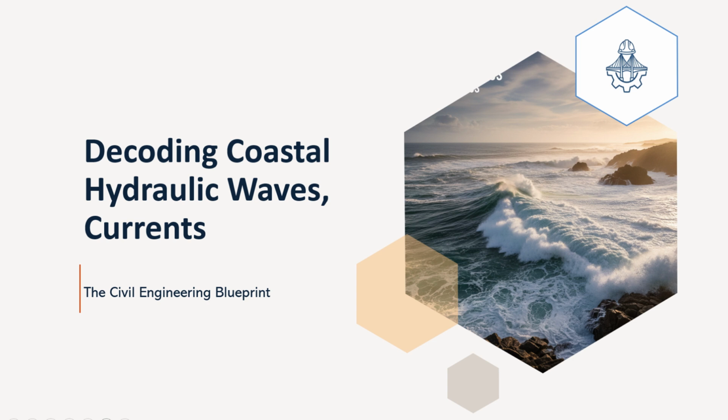Moving beyond reflection, let's consider 4, wave diffraction, the fascinating way waves can sort of bend around obstacles. This happens when waves bend and spread out as they pass an obstacle or an opening, like a breakwater tip or a gap in a reef. Diffraction is crucial because it allows wave energy to penetrate into areas that might otherwise seem completely sheltered. For example, behind a protective breakwater, you still get some wave activity reaching the calm area due to diffraction.